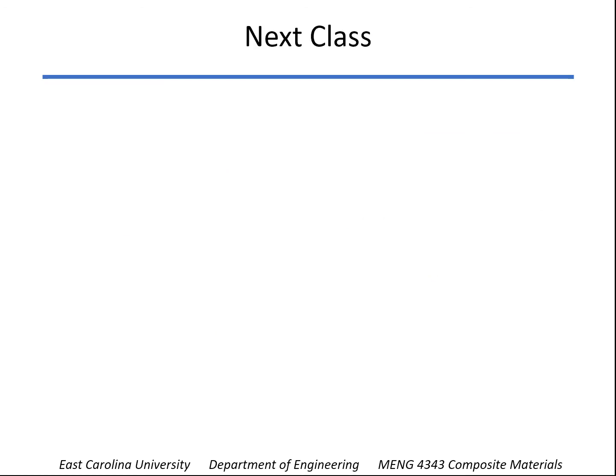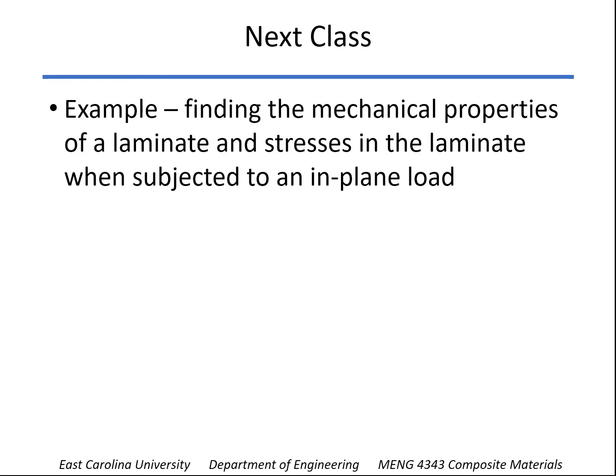Now, that sets us up for doing an example in the next class. We're going to find the mechanical properties of a laminate, and we'll also look at an in-plane load. We'll be able to calculate the stresses in the laminate, or I should say the stresses in each layer of the laminate when it's subjected to that in-plane load.